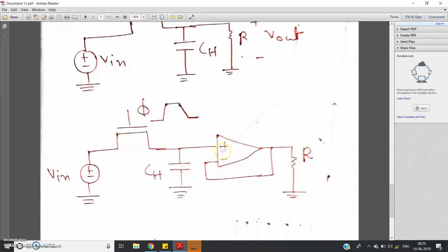So there is no path to discharge, but the constant voltage across the capacitor, or the hold voltage, can go to the resistor. As we have studied, whatever voltage we apply to the non-inverting terminal of the unity gain buffer goes to the output side, that is V input applied at the non-inverting terminal is equal to V output, which we can easily get across the resistor.